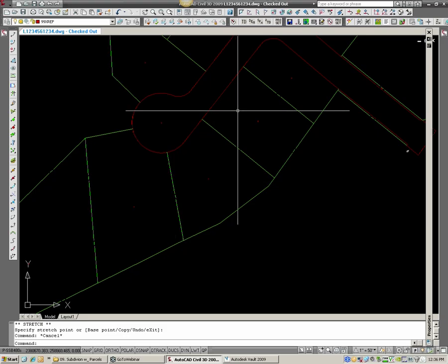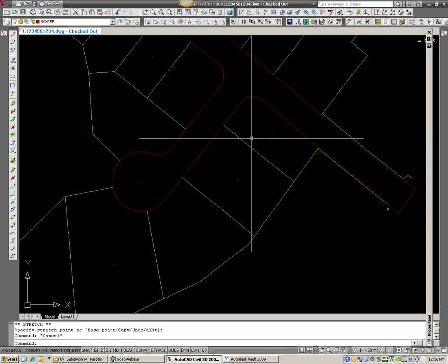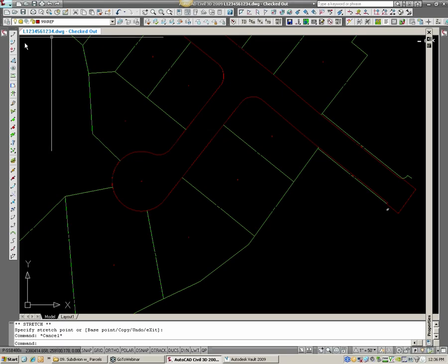So that's a little bit of an enhanced feature if you do use the parcels by layout, and that's really what's going to enable you to edit things faster. If you draw everything with lines, arcs, polylines, and just create parcel from object, you really lose all that. So whichever you choose. All right, so that's the one command.